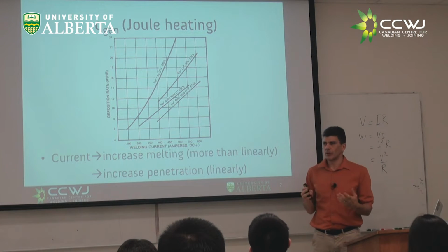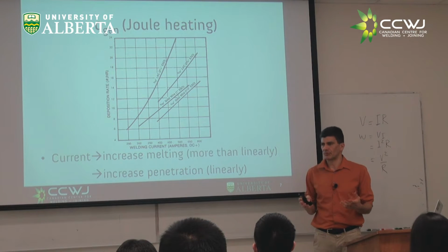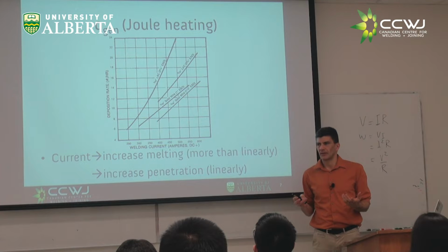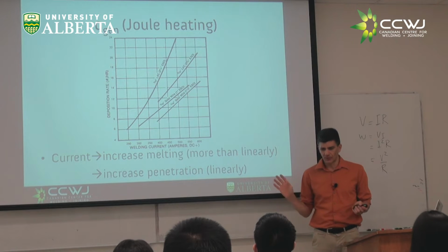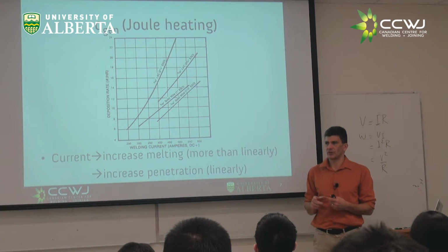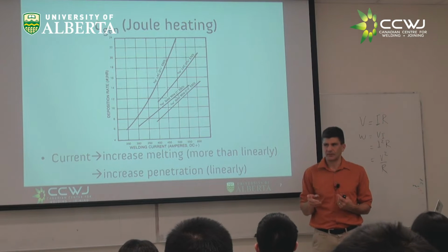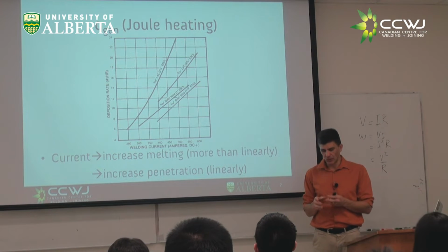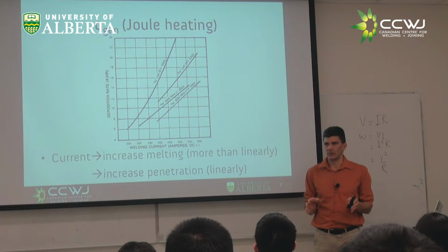Somehow it's not very common in industry. So far, nobody gave me a very good reason. But I can tell you something. Imagine you have your normal MIG machine and you want to have a longer stick out. You have two problems. One is if the stick out is too long, shielding might be difficult, right? Okay, but we can deal with that.